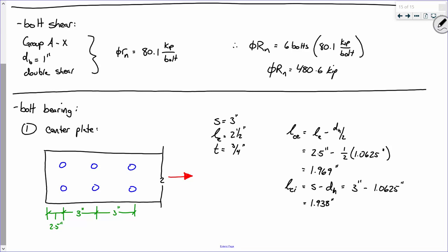Now, what really could happen is a staggered connection. If you've got that checkerboard type pattern, you just have to be diligent in your bookkeeping. Look at the edge distance on this one, the edge distance on this one, and et cetera. I won't do that on an exam because it doesn't become hard. It just becomes more bookkeeping, and then it's not really a test of the materials. I won't do that on an exam. I might do it on a homework. When you're measuring on a stagger pattern, do you go between just this set of bolts and then the next set of bolts, or then matching?